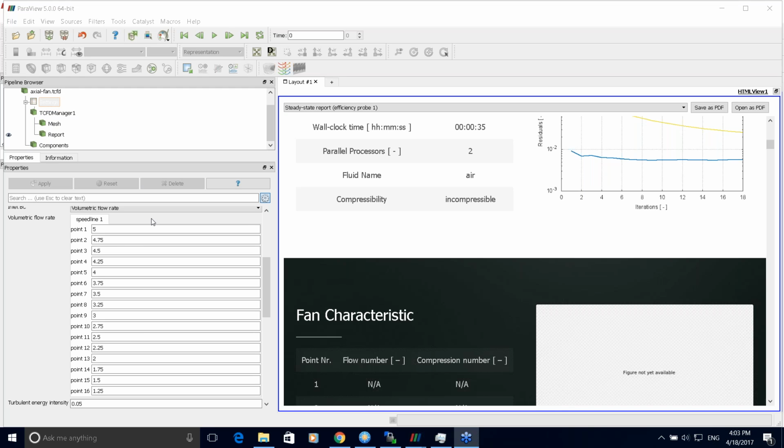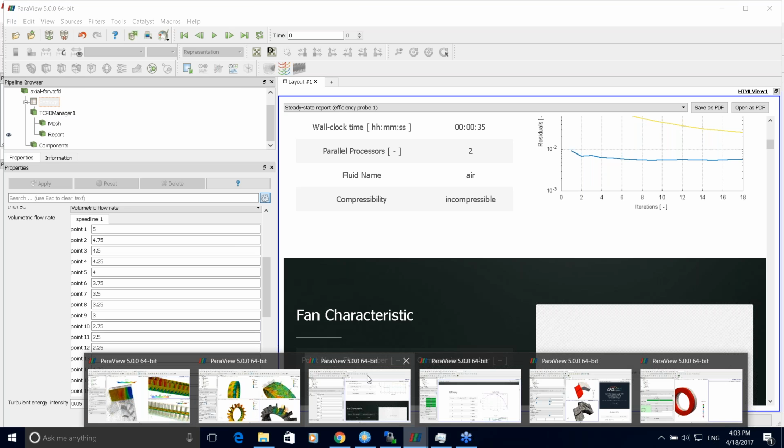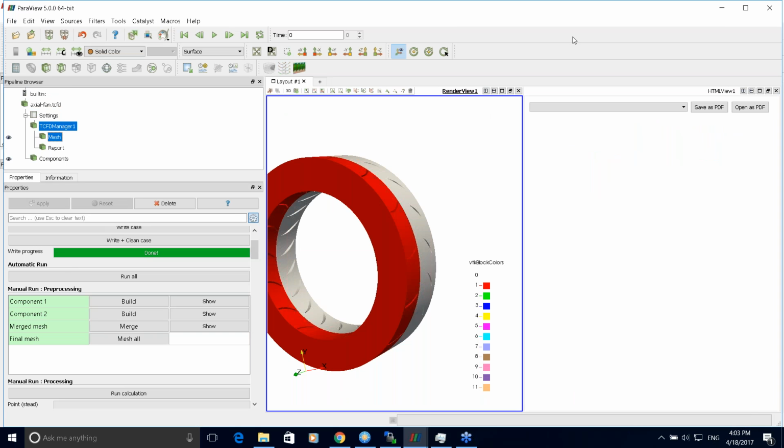What is the STL mesh? So how is it different from external OpenFOAM meshing? Okay, so there are two options for how to define the computational mesh. The first one is to use the in-house Snappy hex mesh tool, which needs the STL files, which is just the surface